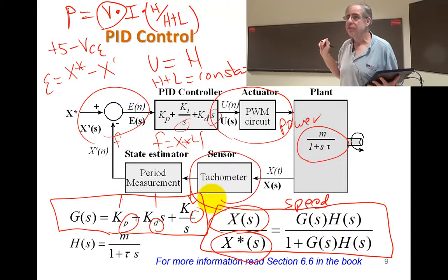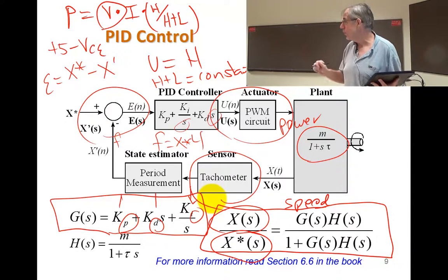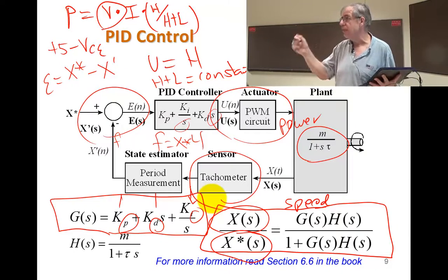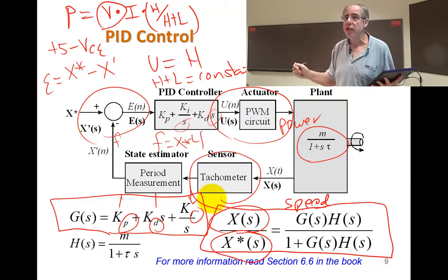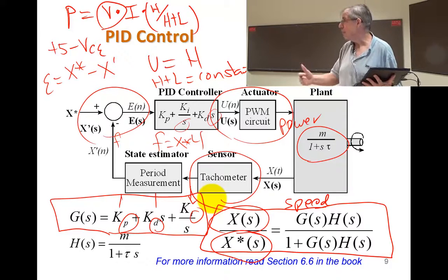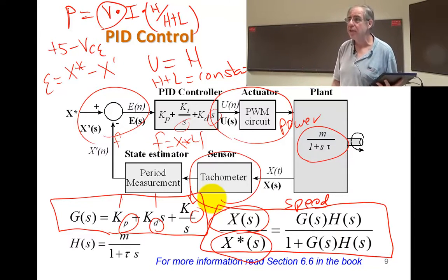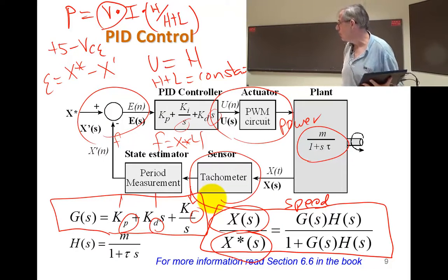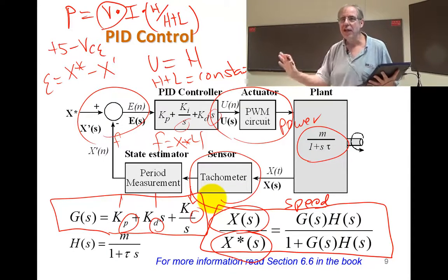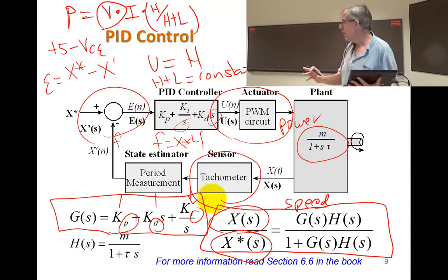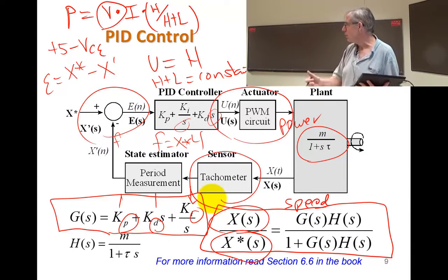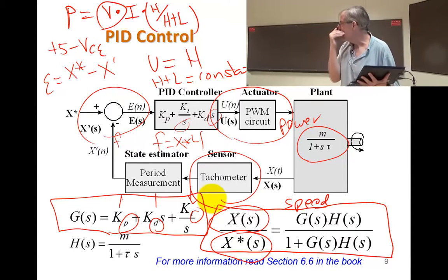And it's not linear, because I can adjust the duty cycle from 0% to 5%, and it doesn't do anything. No respect. I go to 10%, it's still sitting there doing nothing. And I get to 25% and it pops up real fast. Okay? So it is a nonlinear system that cannot be adequately described with a differential equation.